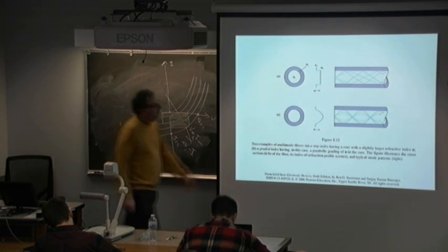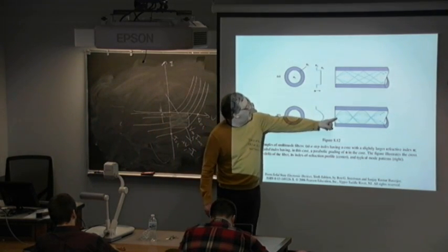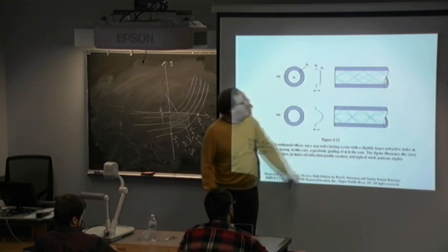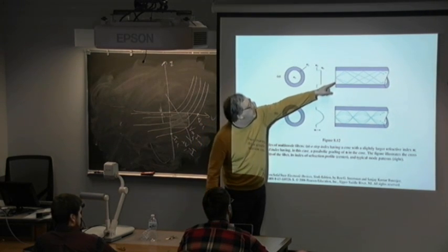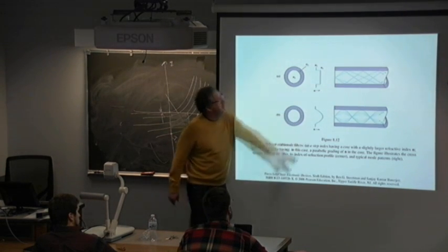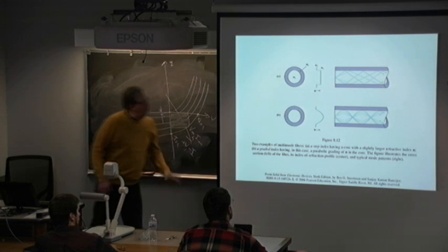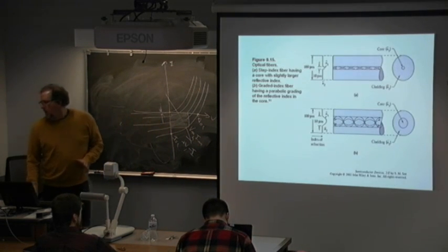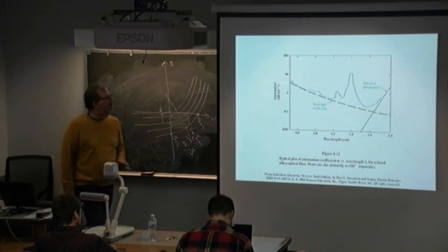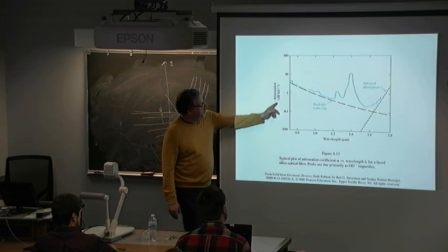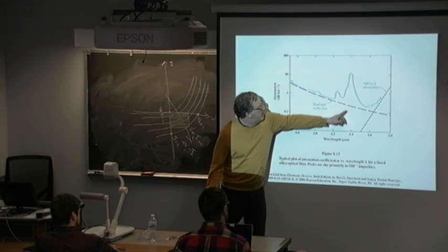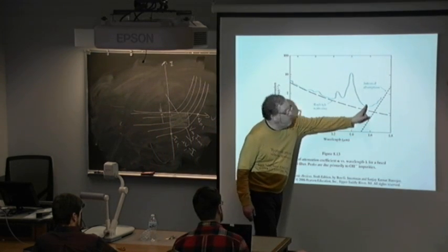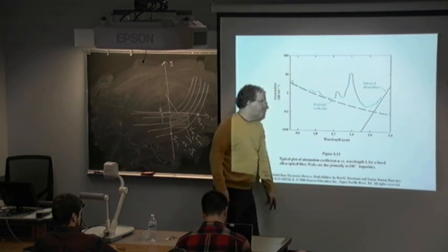And here's your dispersion-correcting fiber, or actually dispersion-less fiber. And here's your normal old-school graded-index fiber, where the ray tracing causes the corruption of the signal. And here you can see the dB, the attenuation of the fused silica. So usually you're operating at 1.55 microns.